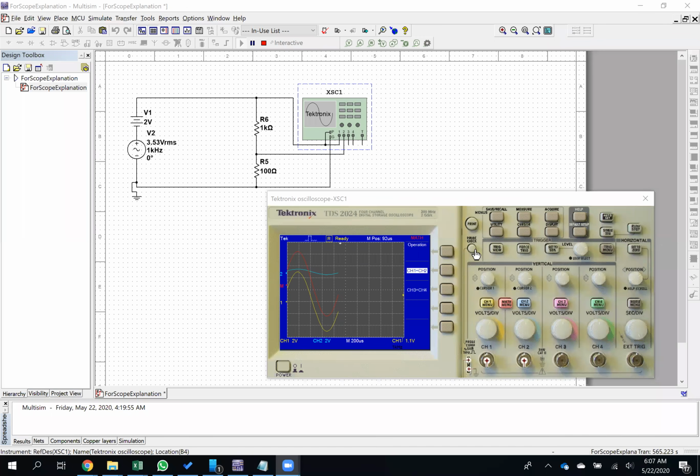And the first thing I noticed looking at this is that it doesn't seem to make sense. I wanted channel 1 minus channel 2, but then I realize when I look at the menu, I've selected the plus operation when what I wanted was the minus operation. So let me select the minus operation and reposition my waveforms, and now I can see that the red waveform is actually smaller than the yellow waveform, and that makes sense because the red and the blue waveforms here should add up to the yellow waveform.